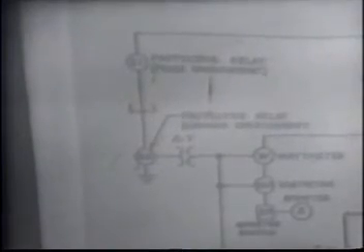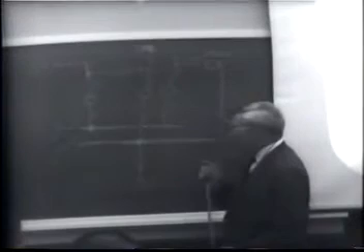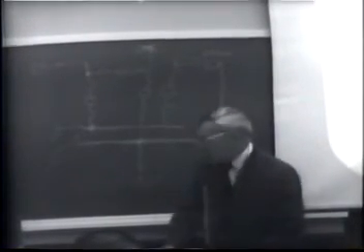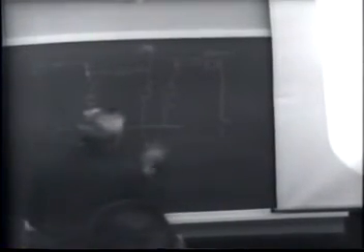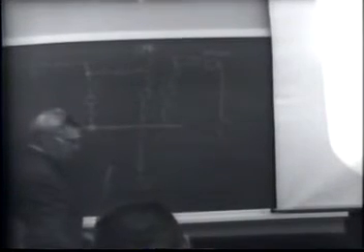I think we're open to questions at this time. Is the sub 56 line going to be tied directly to the bus, or should there be another breaker? Well, the circuit breakers for the sub 56 line, you see, what I have here right now is sort of a combination of the expanded breaker and a half scheme. Let me go back to exactly what we will have when the sub 56 line goes into service.